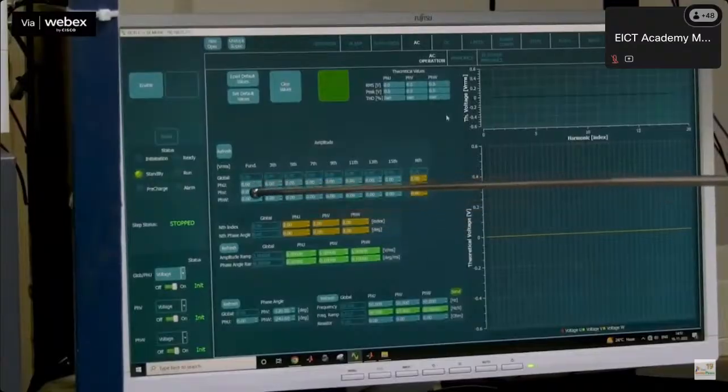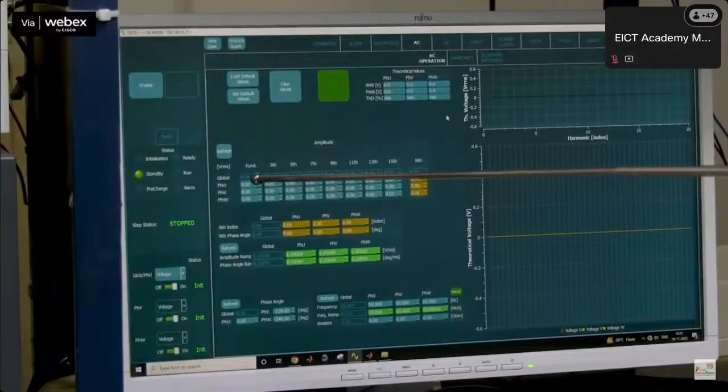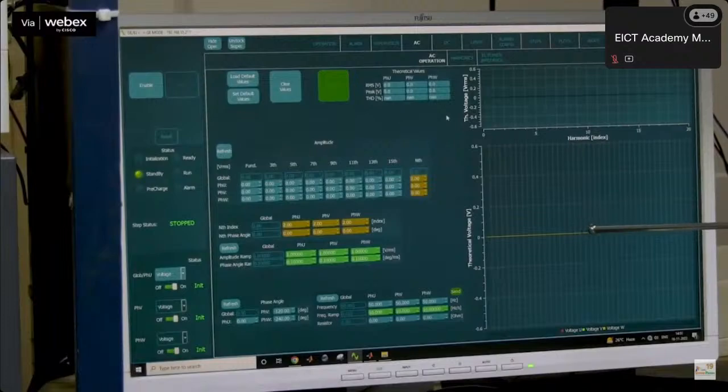Desired voltage values need to be entered for the 3 phases in the AC operation section of the software. Apart from just entering desired voltage values, it is also possible to monitor grid voltages during experimentation. After entering desired voltages in AC operation, the voltage and current limits need to be specified in the limit section to ensure the safe operation of the system, or in other words, so that the voltage does not exceed the operating value that you desire during the experimentation.